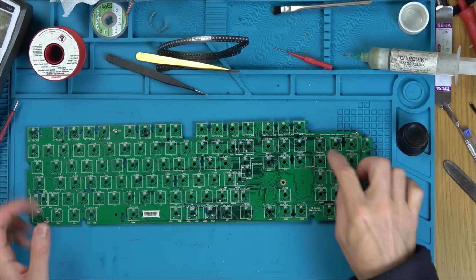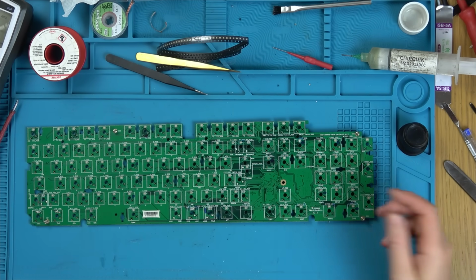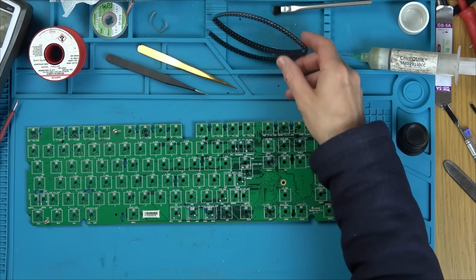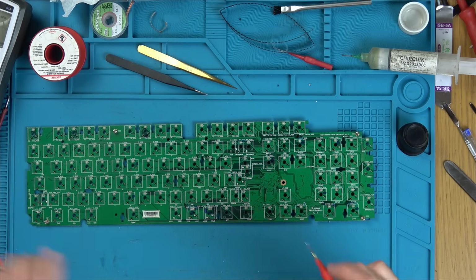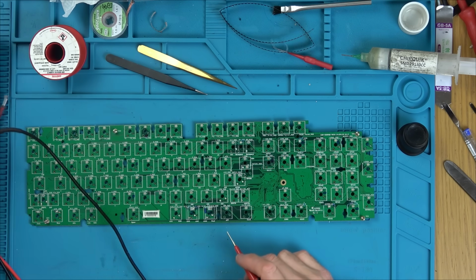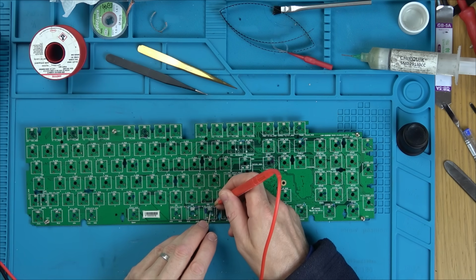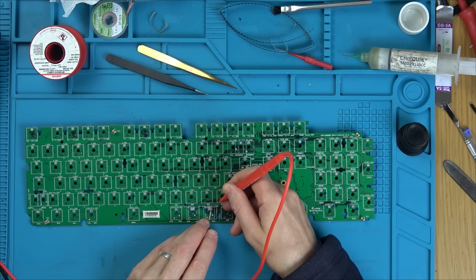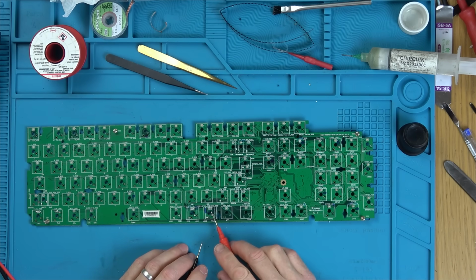Some of the ones that I've marked, like this one here and this one here, are ones that I've replaced already. Now, there is a chance that the new ones could be faulty, as in, they might not be showing blue. I just think it's highly unlikely. But there are others, I've got it on diode test, like this one here, which is next to the one that I've replaced. That will work on a little red light, yeah, but it won't work on the green light. And if I go to the new one on the green light, you can see that it's lighting up there. So I need to replace that one.